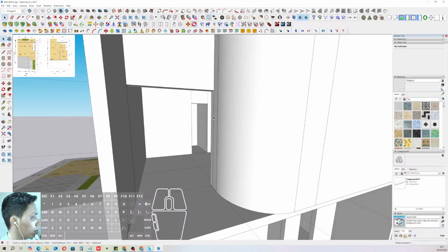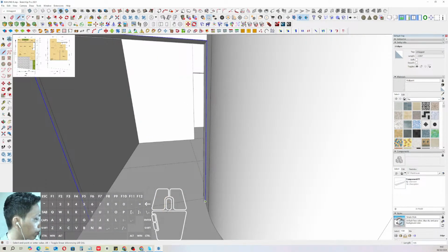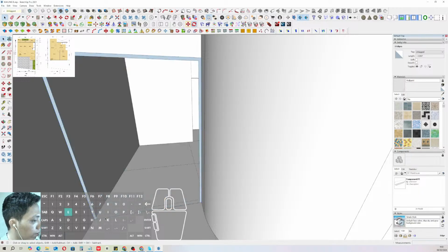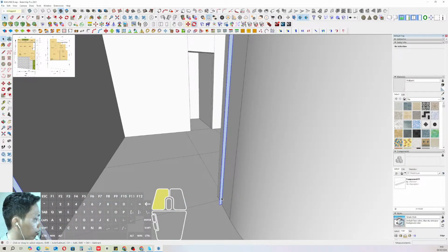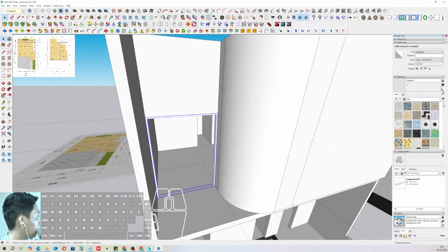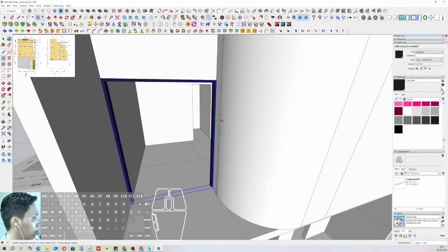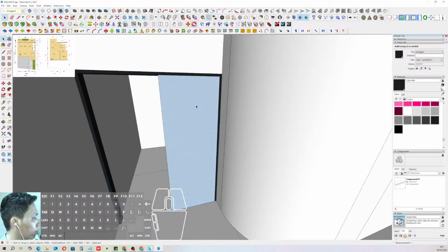And then we can make the door, especially this glass sliding glazing door here. We can type the frame 35. Then we can push it to the behind 120. Make group, then assign another material using dark or black materials like this, and just select the sliding window.